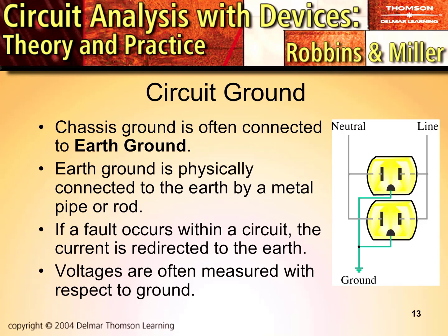The protective ground or safety ground is there on every receptacle or every appliance, and it's used whenever you're working with an appliance or a tool or an electric device that has a metal chassis or a metal body or a metal handle, where there's a risk of shock.